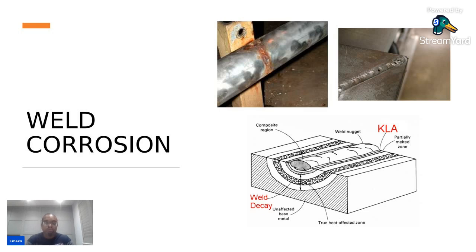So, bad welding can lead to different things, such as erosional corrosion. Also, with the parts protruding, if it's not done properly, if there's flow through that section, it becomes a location where there will be turbulence, and therefore leads to pitting corrosion as fluid flows through it. Where does this type of corrosion occur? Weld corrosion is commonly found in oil and gas systems, such as seawater systems containing CO2 and high acetic acid environments.